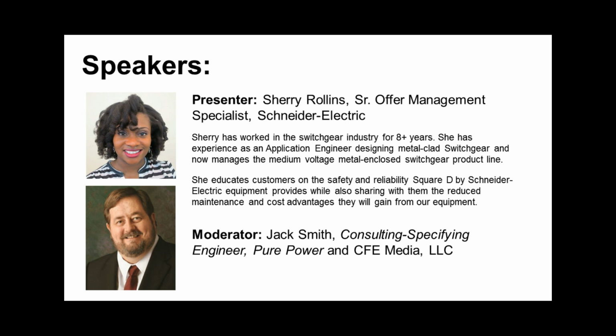Less expensive, I think Sherry talked about, or even I answered a question previously about how fixed-mounted switchgear could potentially be somewhere 15% less expensive than withdrawable switchgear. I think we also saw a message throughout this presentation about some improved safety aspects in fixed-mounted switchgear. We talked about having the ability to have integral grounding switches. I think Sherry mentioned potentially having interlock sequence of operations where it ensures you've got safe operations by whoever is operating or maintaining the switchgear.